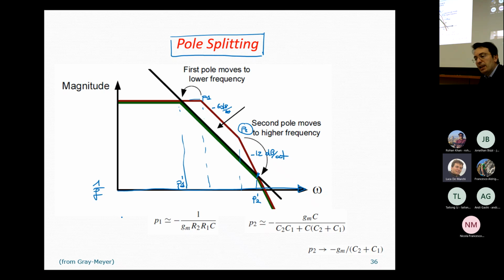So in our circuit we have two negative poles and one positive zero. Okay, so what we can say is that our phase will be the combination of the effect of pole number 1, then the effect due to pole number 2, and then the effect of the zero. Okay, and these effects are those indicated by this formula.